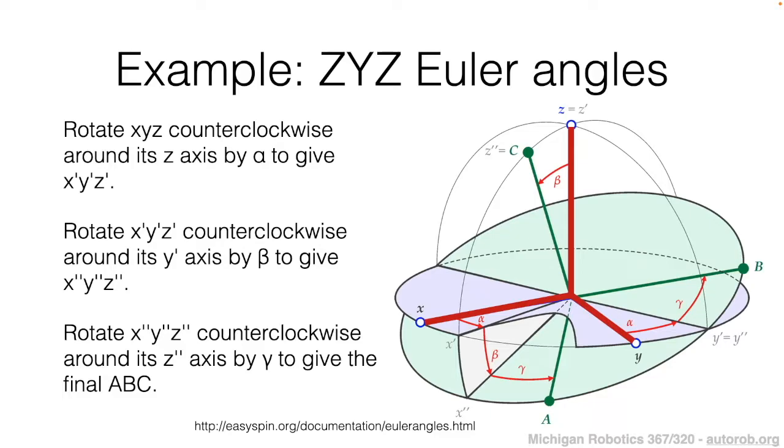On this slide we'll illustrate this series of rotations, where the red vectors that we've drawn here along the x, y, and z axes denote the frame as it's being rotated. The crucial aspect of Euler angle transformations is that as we apply the rotations, our coordinate frame is getting modified. And so an initial rotation about the z-axis is not necessarily going to mean the same thing spatially as a down-the-line rotation about that z-axis.